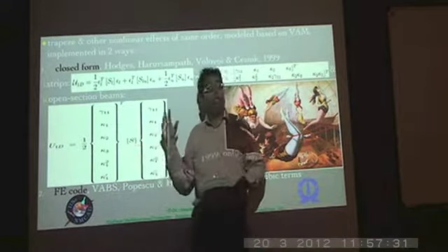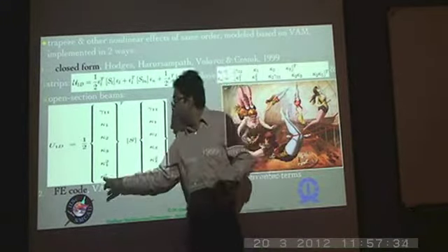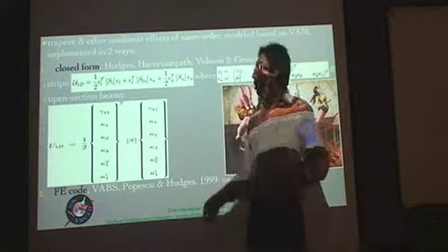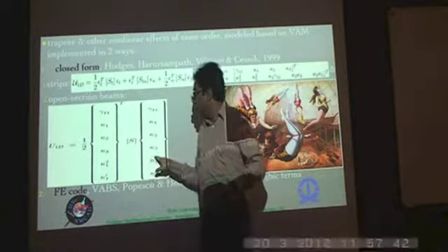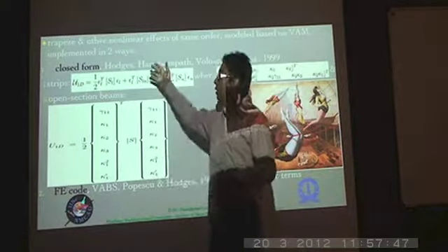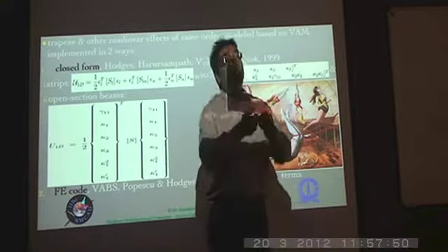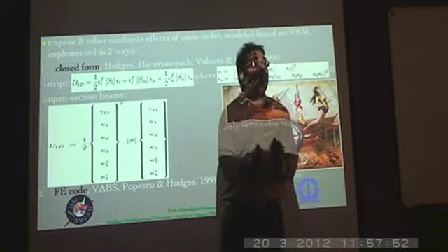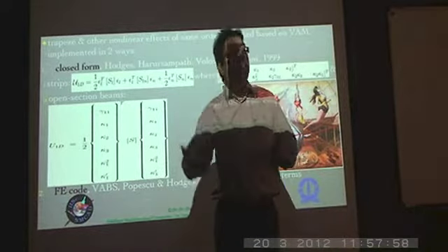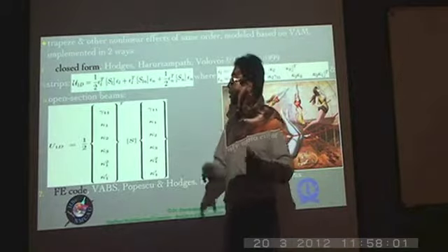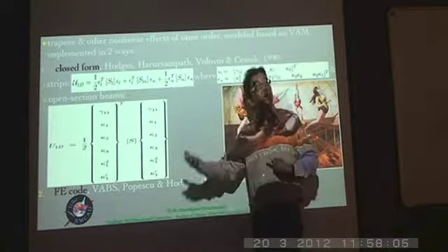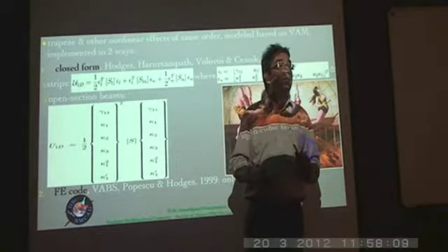Once again, S is a matrix of constants, but now you see that, of course, we have this kappa 1 prime, which is a restrained warping effect, which we talked about earlier, but there is also a nonlinear effect that you see here through this kappa 1 squared. A thin-walled open section, unlike a strip, has the same order of magnitude of bending curvatures in both directions, because the stiffnesses are of the same order of magnitude, be it a T section or an I section or whatever. So there is no order of magnitude difference between the bending curvatures in both directions, because there is no order of magnitude difference in the bending stiffnesses in the 2 directions.